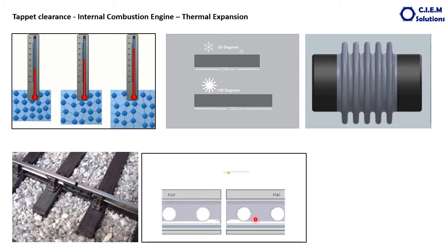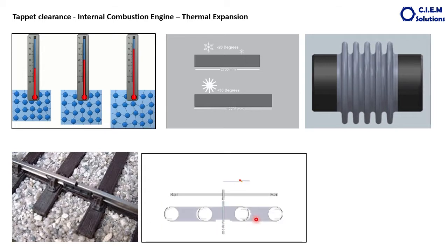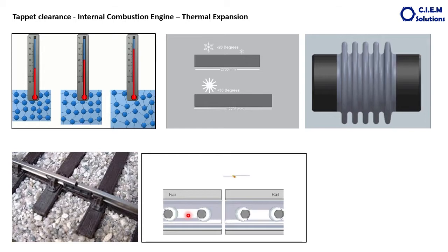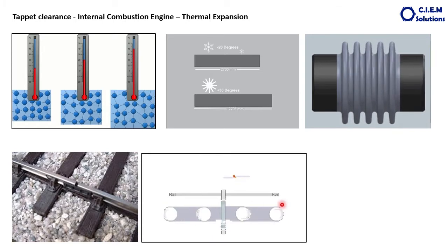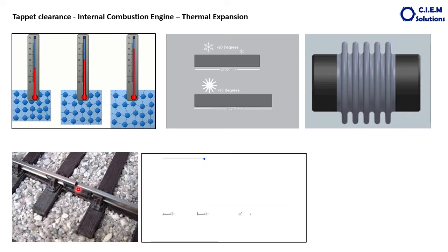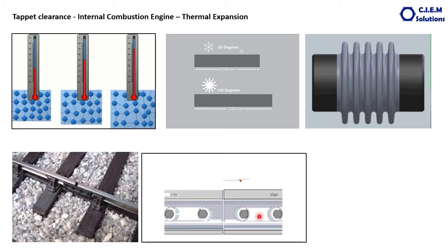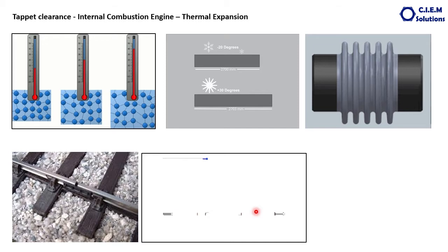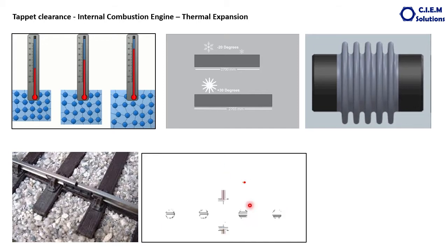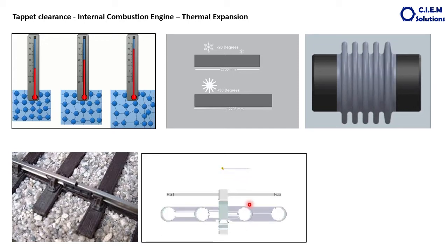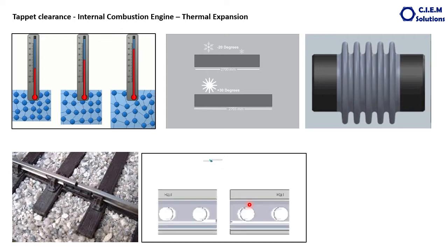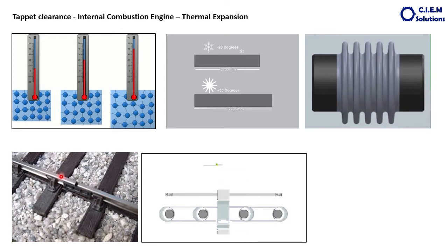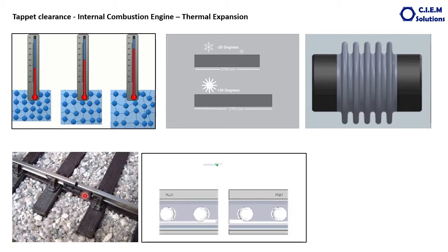Rail is a steel material, and this is how steel behaves with a change in temperature. So this gap is provided to take care of the expansion when the rails attain certain temperatures because of the running of the wheels, the friction generated by the wheels running on these rails, the change in the atmospheric temperature, and so on.